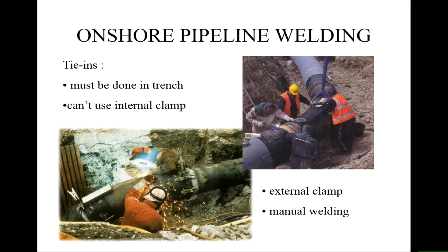So you can see a bend being put in here. There's a welder working on one side with a stick. There's a welder on this side who's also working with a stick. You can't actually see it. And a couple of safety guys standing beside just in case something happens. The clamping is not really done very strongly, it is fit up by positioning. So you have some underneath supports, you get the bends into the right sort of position, and you line everything up as best you can.